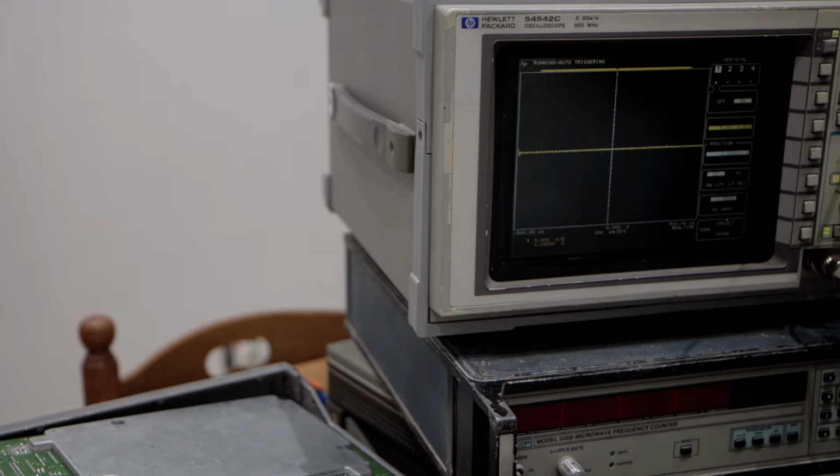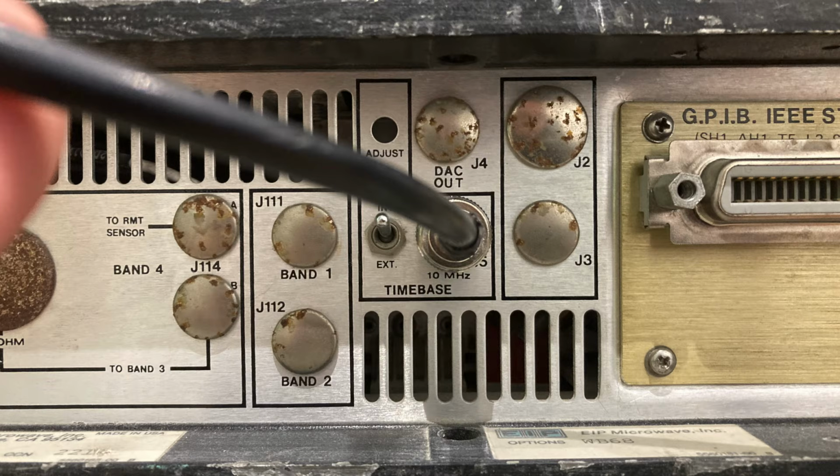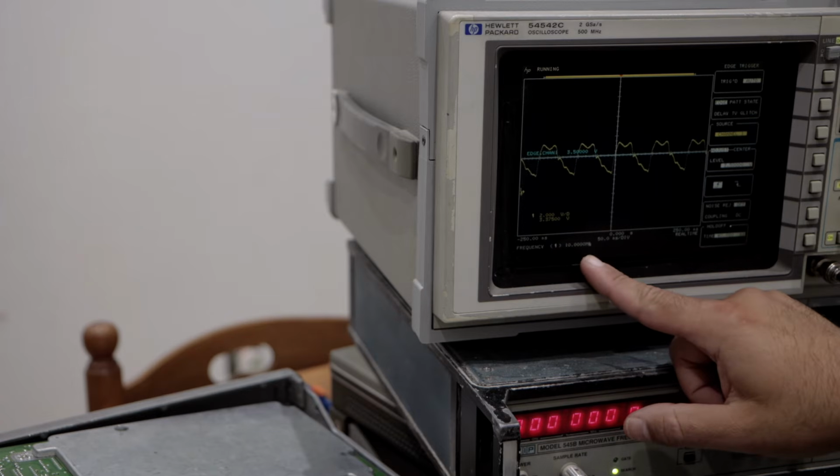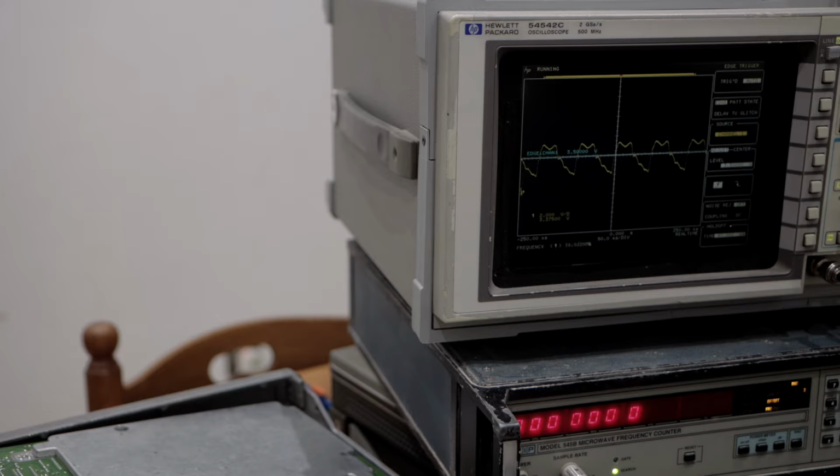Now I have my frequency counter here, and it has a 10 MHz output. I use it to test if the spectrum analyzer responds. The analyzer expects a signal of 0 dBm, but this one seems stronger. Maybe I forgot to switch back to no attenuation on the scope. That probably explains why. The signal I'm getting out of this frequency counter isn't perfect, but it's a solid 10 MHz, so it should work for a quick test.